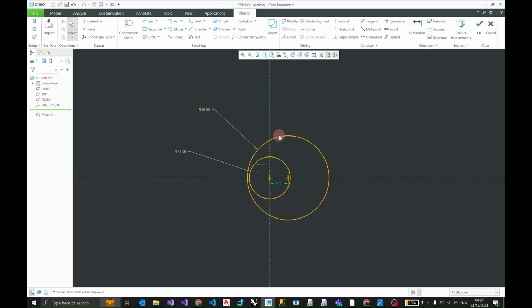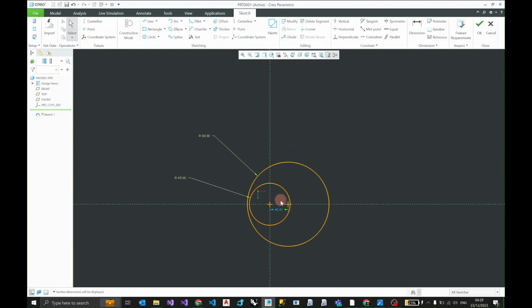So now you can see the dimensions have been changed, but I can drag them, and the dimension can dynamically change because it's not fully constrained. So I'm going to change the radial dimension back to 90, and then left click it once and press this lock command, which just says toggle lock, to lock this dimension so that it cannot be changed any further. So it's fully constrained now. Same thing with this. Press this and its dimension cannot be changed.